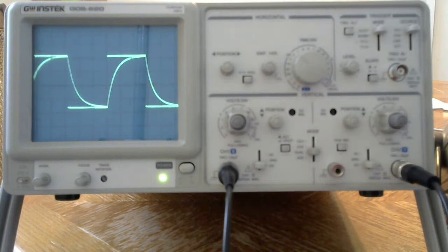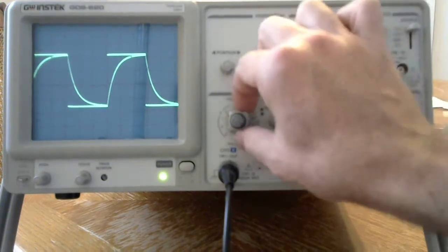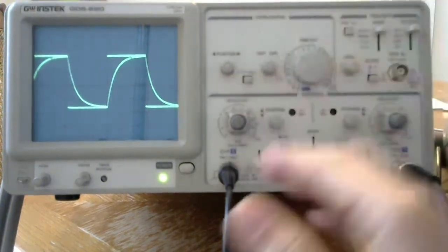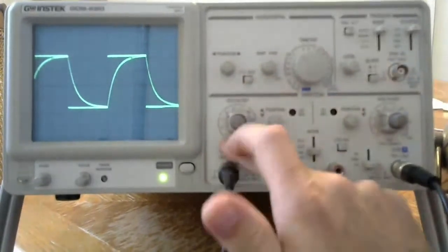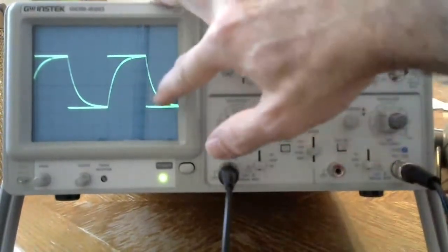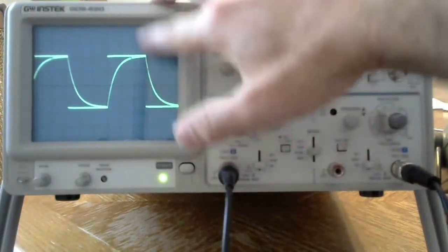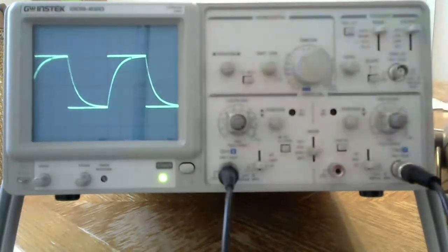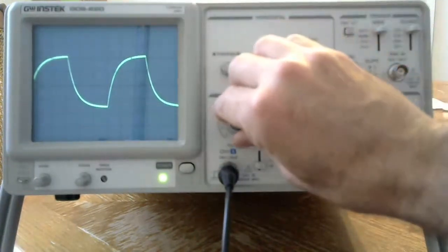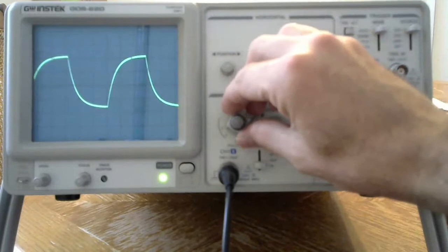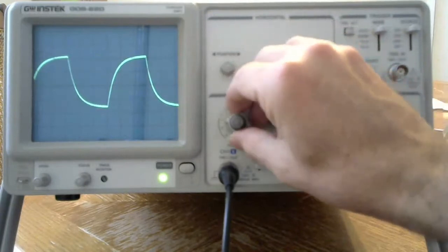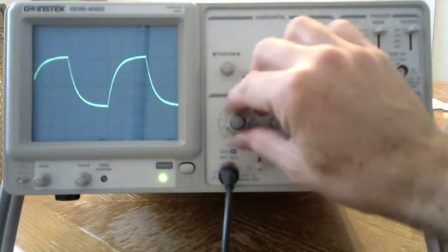And I can change the scale, okay? So again, I'm not changing the signal itself. The signal is whatever voltage it is. But I have here my volts per division set to, right now, 5 volts per division, okay? So 5 volts per division means that each box vertically represents 5 volts. If I turn this, each box now is equal to 2 volts. Here it's 1 volt.